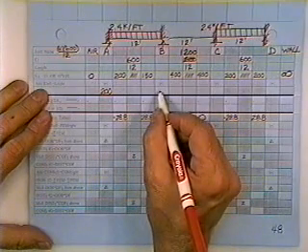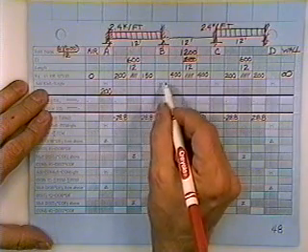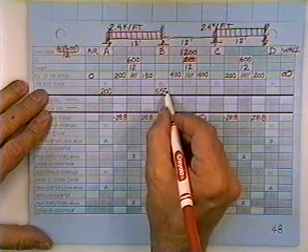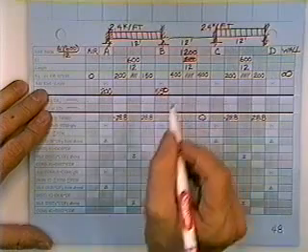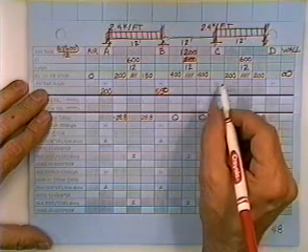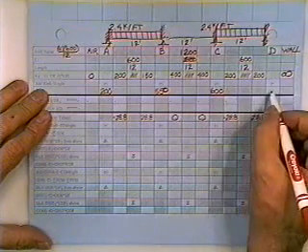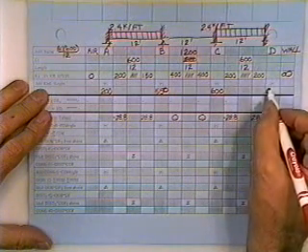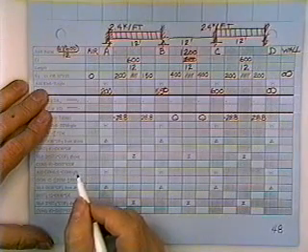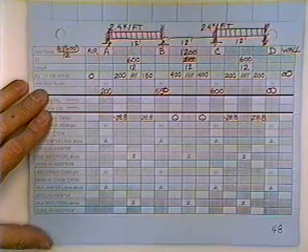You go right under joint B and you see how stiff joint B is. You add the number to the left, 150, plus the number to the right, 400. 550 tells you how stiff is the total joint. You go to joint C and you say how stiff is the joint? 600. And you go to joint D, 200 plus infinity is infinity. It's really stiff. And the wall would be really stiff. It wouldn't have much flexibility like a member would.